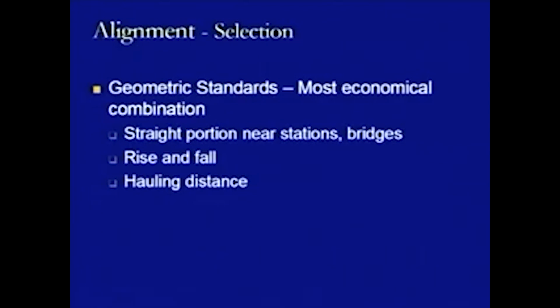The requirement of providing an embankment or the requirement of cutting, both of these things are costly affairs, whereas cutting is a more costly condition as compared to filling. Therefore, we have to balance out the total quantity coming out from cutting and required in filling, and that is how the rise and fall has to be balanced out as far as the material considerations are concerned, as far as it is possible. If it is not at all possible, then only the cost escalation may be allowed.